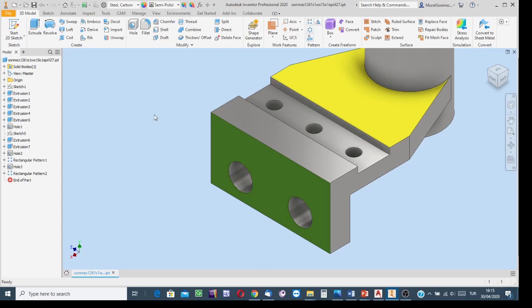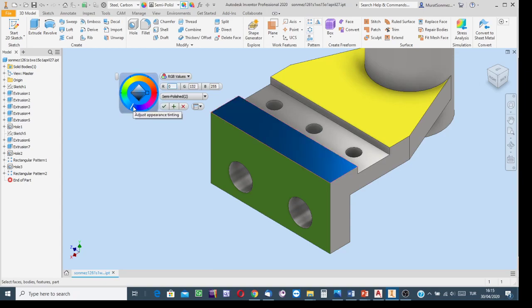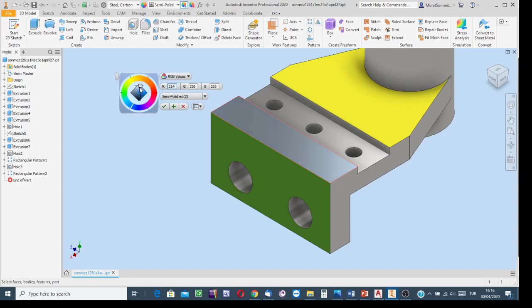Click on the OK button if it is the only surface to paint. But if you have some other surfaces, instead of clicking on the OK button, click on the Apply button. Okay, one more demo. I selected the surface with a click, and then the main color from the ring, and then bring the cursor onto the diamond, hold this square, and change the color density, darker, lighter.